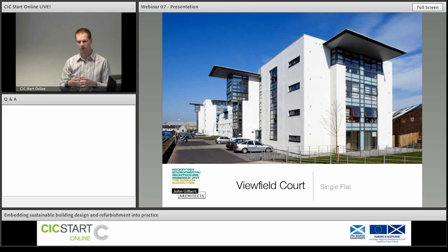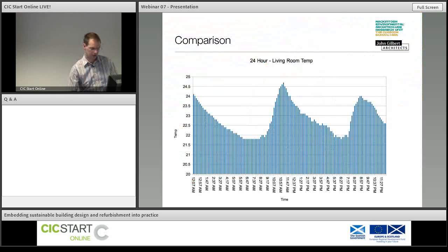There's solar gain of some sort at particular times during the day, and the living room is seeing really big spikes, and then obviously the windows opening to get rid of that heat. And again, you wonder if in the winter that still happens, and whether there's heat being dumped out through that. It depends on the particular flat. It's only a bit of a hypothesis, but that's probably the main thing to note from this, that it seemed to be quite a lot of solar gain.